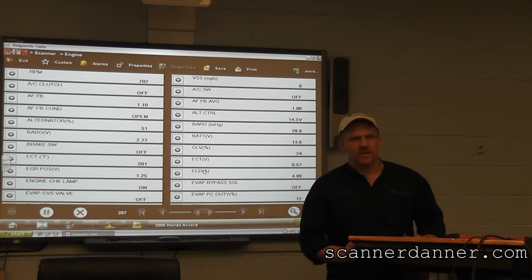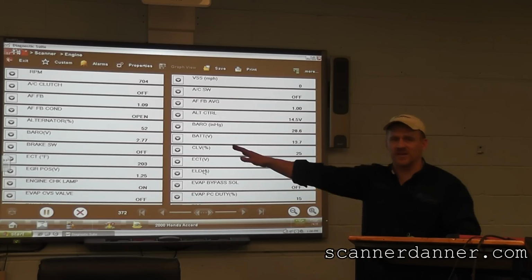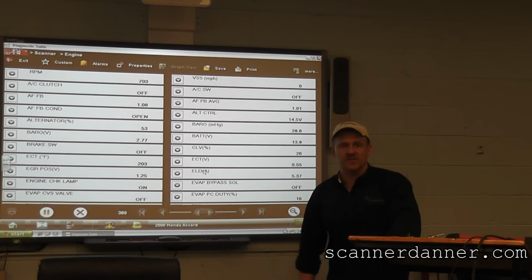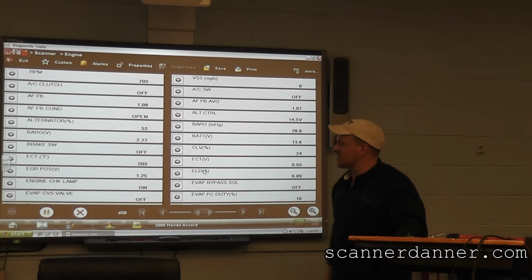So I don't remember how the lambda number works. If it's numbers above 1 and numbers below 1, which way it's rich and lean. I'm not totally sure on that. Numbers above 1 would be rich. Numbers below 1 would be lean. So it's opposite of what we would see with an O2 signal. And again, that's a calculated number you're looking at. You guys need to understand this wideband sensor. We don't have any voltage readings on this wideband sensor at all. You're looking at completely processed data.